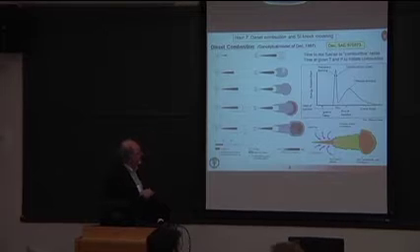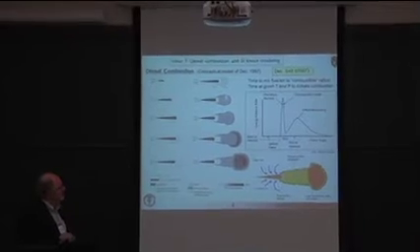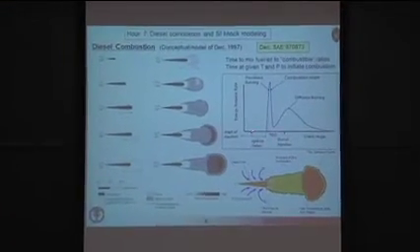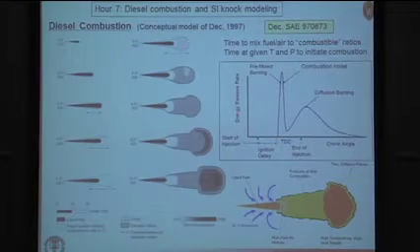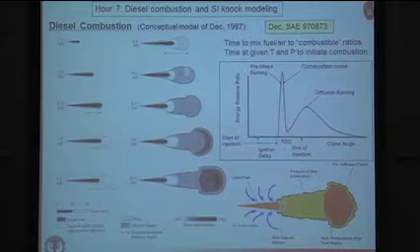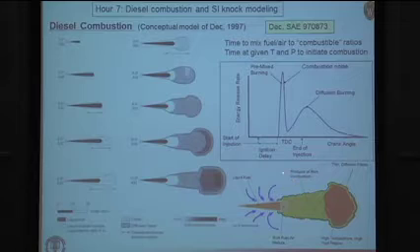If you look at the picture shown here, this is a typical heat release rate diagram. We discussed this briefly once before as well, where you start injecting over here, so that's back here someplace, and at a certain moment combustion starts. So all the fuel that has already been injected essentially spontaneously combusts, producing this very sharp premixed burn. The fuel and the air have had time to premix. And then following that, we have what's called diffusion burning, where now we rely on the transport of air into this fuel-rich region to establish a diffusion flame.